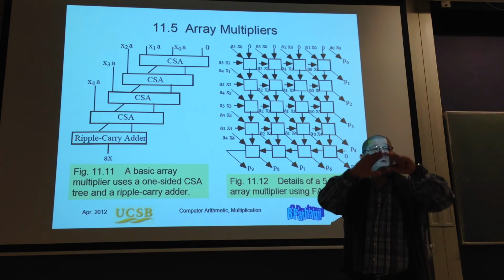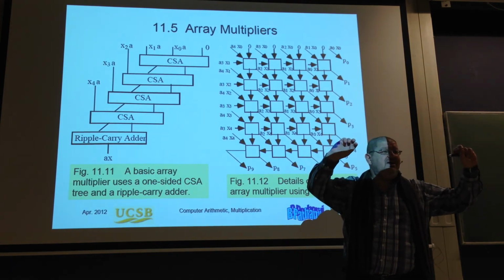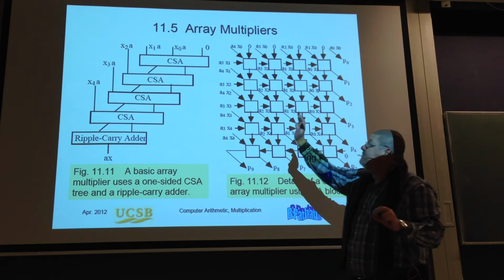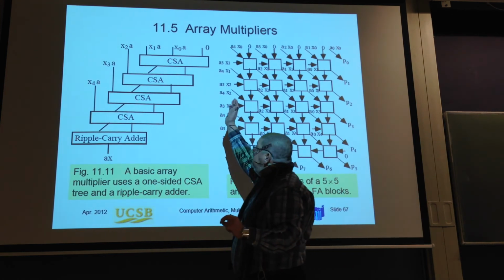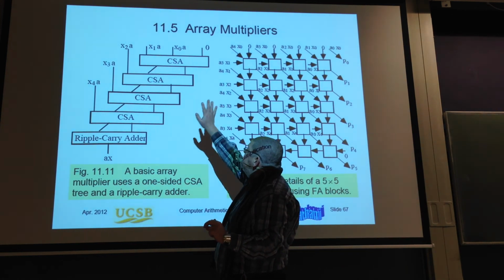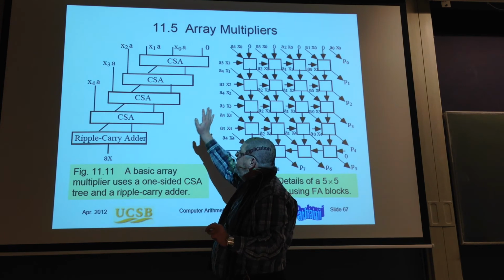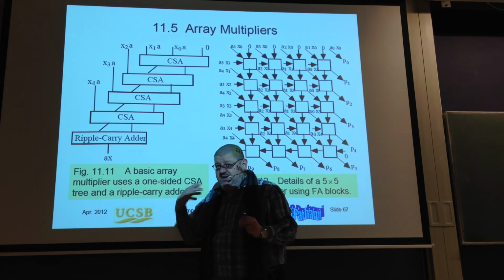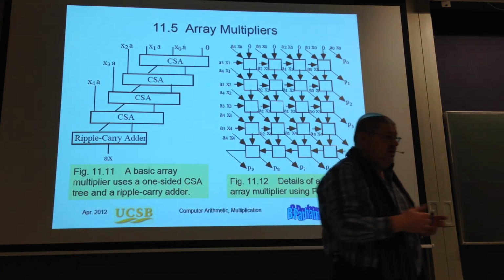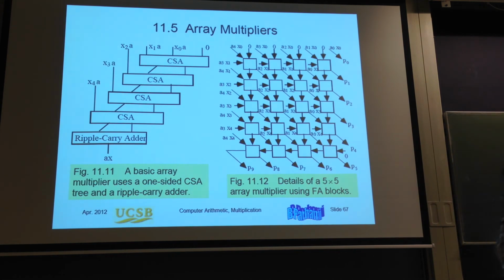Then I'm not pushing parallelism to have a real tree, but I am taking them in pairs. Then I'm adding one more partial product. It's the same philosophy. Then I have all the partial products, I'm applying a reduction, but now my reduction is not a real tree, it's a degenerated tree, and I have a final adder.